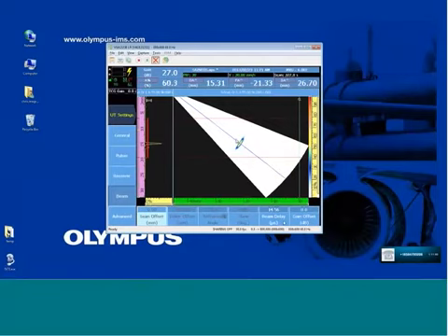So in the instrument now, we have a single group of a 16-element aperture. So to manipulate the S-scan, we're going to use a series of function keys and or menu items. Select function key data cursor, shows me the angle and allows me to manipulate the data cursor here.